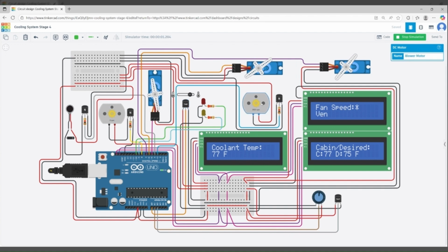This is going to be our blower motor. We can see we're at 2600 RPMs currently. This is going to be our blendDoor actuator. Adjust the flow, whether it's going through the heater core, the evaporator, or a little bit of both. And then here's our vent actuator.